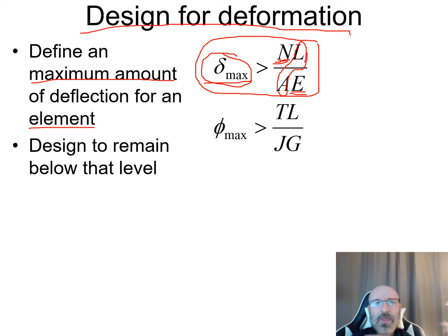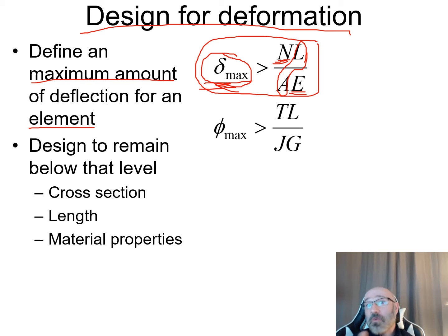What we really want to do is say, okay, with that material, what dimensions do I need to make it in order to stay less than our max deflection? That's where we can use this relationship and try a couple of different ones out. And this, again, is a great opportunity to start getting into some of these numeric solvers. We want to find the value that is just less than our delta max, but still keeping our cost and weight down, which are always big factors: cost, weight, and size. We want to keep those minimal. So we want to make that L and A the smallest we possibly can, but still keep this under our max deflection for this problem.